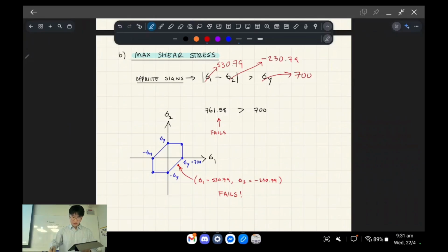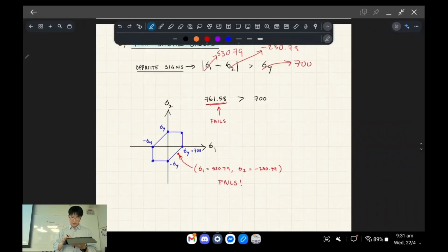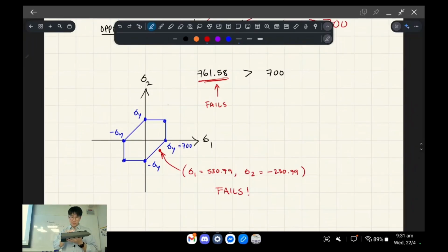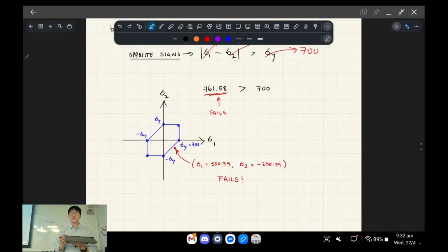And the yield stress, right? You see that because this time it's greater than the right-hand side, we've actually got a value which sits outside the failure envelope and it fails. Okay, so this is an interesting case where when it's contained inside the oval, it doesn't fail, but when you're using the first theory, which is more conservative, it does fail. Okay, so that's what this question's trying to illustrate. So does that make sense?